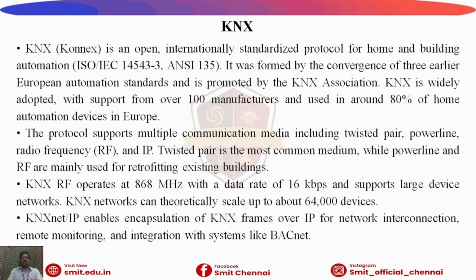KNXnet/IP enables integration with IP networks. It supports large and scalable installations. KNX RF operates at 868 MHz with a data rate of 16 kbps. KNX networks can theoretically scale up to about 64,000 devices.